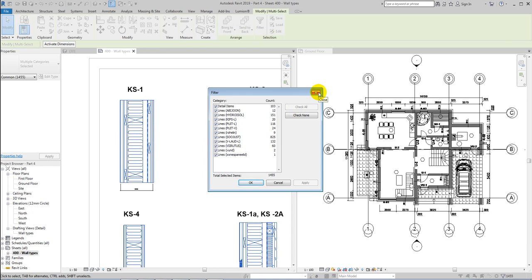In Revit you cannot scale detail items. That means that we will need to delete them and then rescale it, or it's better always to check straight away after import of CAD which scale it is, and currently it is wrong.